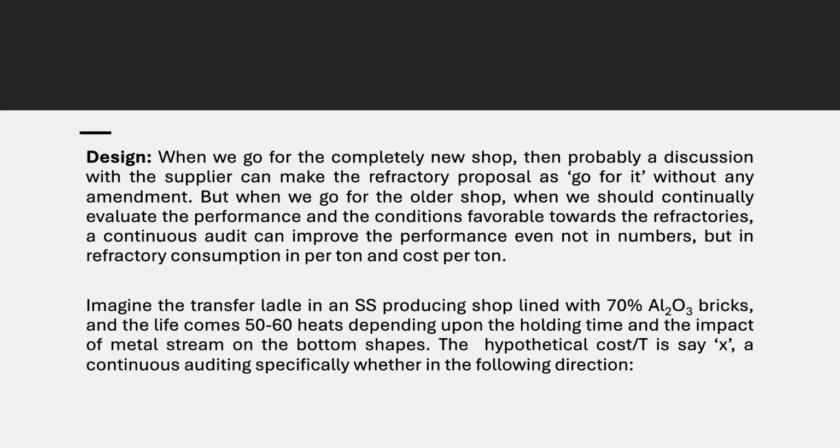Imagine the transfer ladle in an SS producing shop lined with 70% alumina bricks, and the life comes to 50 to 60 hits depending upon the holding time and the impact of the metal stream on the bottom shapes. The hypothetical cost pattern is, say, X. The continuous auditing would go specifically in the following directions.